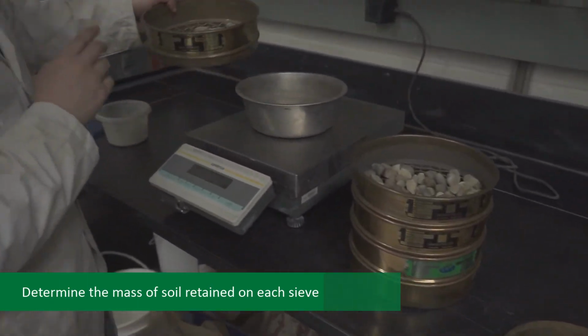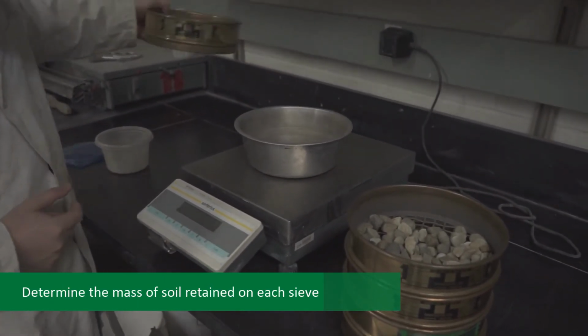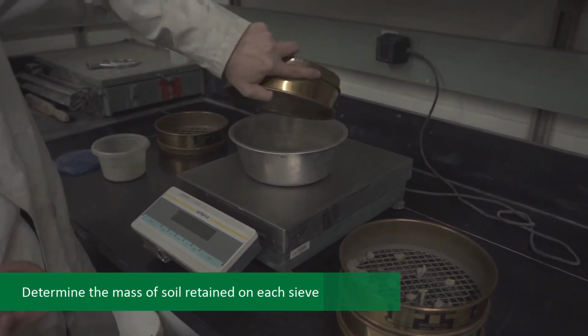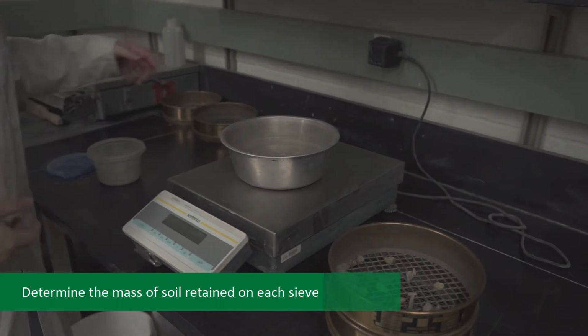You should now determine the mass of soil retained on each sieve by emptying the contents into the metal tray and weighing on the balance. Empty as much of the soil as possible into the tray using the sieve brush. Record all measurements on the datasheet provided.